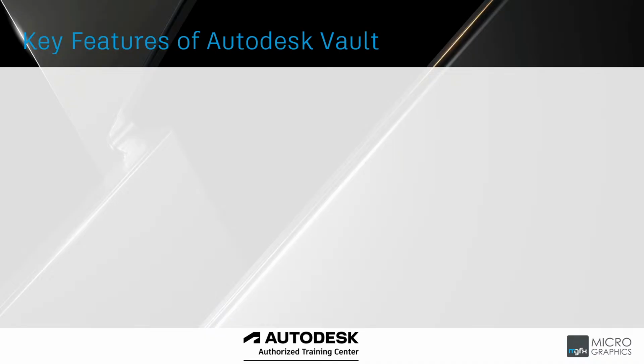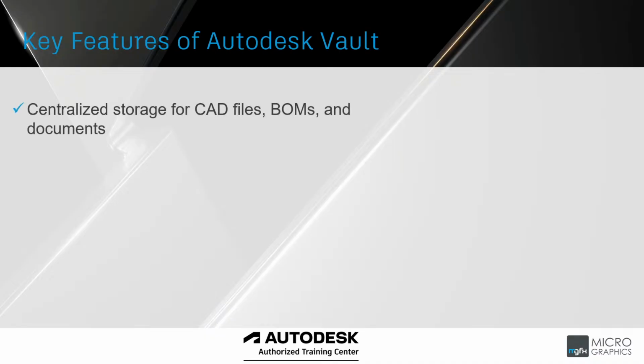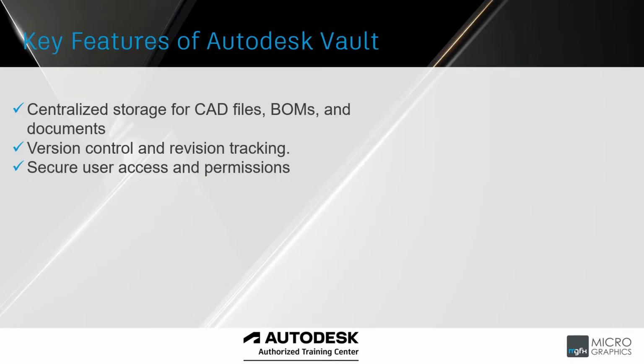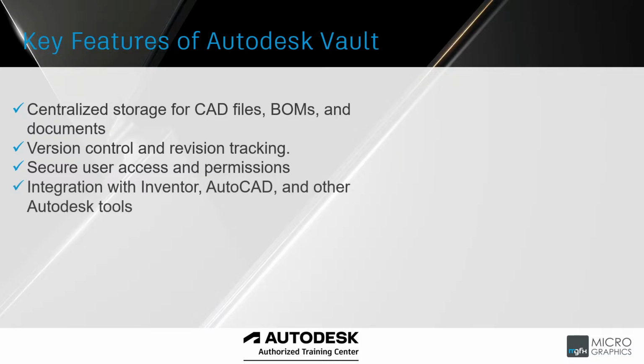What are some of the key features of Autodesk Vault? It centralizes the storage for CAD files, BOMs, and documents, where you can even upload Office documents into your Vault, like PDFs, Word, or even spreadsheets. You've got version control, and if we think about Vault Professional, you also have revision tracking, secure user access and permissions, and it integrates with Inventor, AutoCAD, and other Autodesk tools.